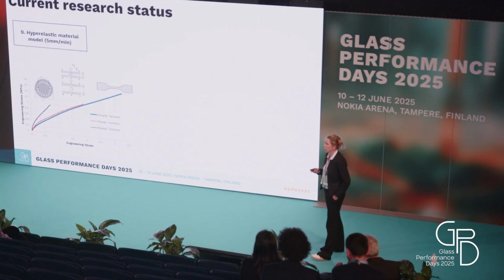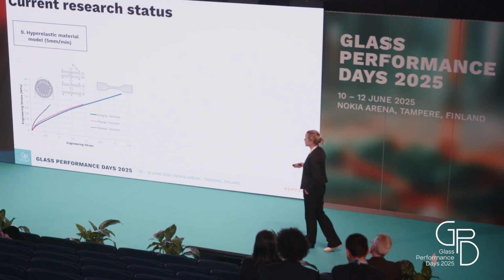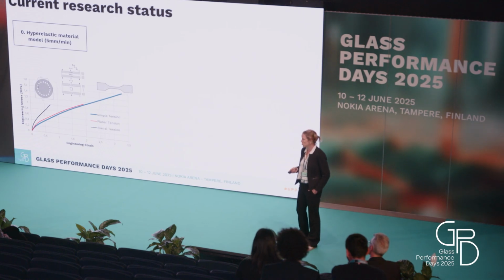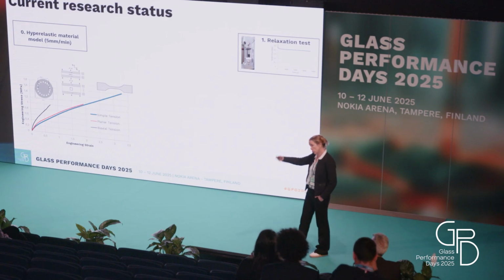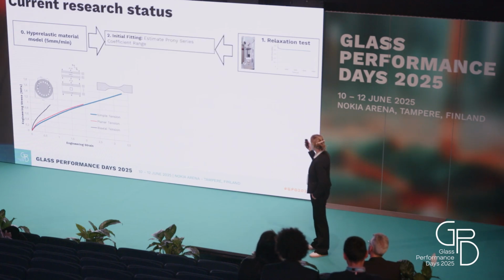We have, as you may know, determined material models for most of our structural glazing, insulating glass sealants, and weatherproofing sealants globally, based on normal pure deformation mode testing: the uniaxial, the shear, and the compression test. And now to go further and to introduce the dissipation character, we are introducing relaxation tests.